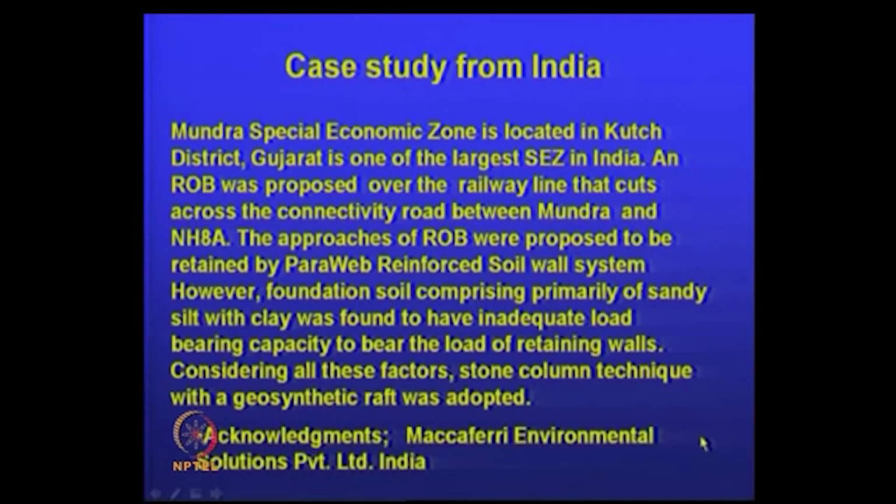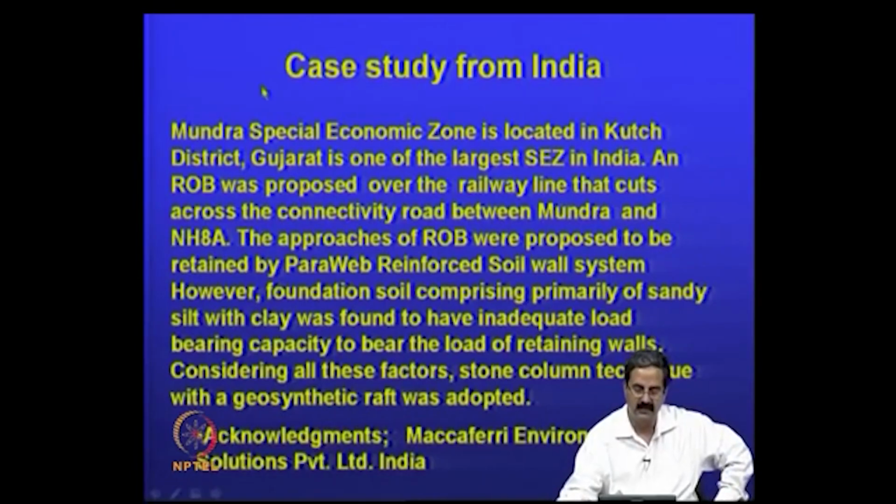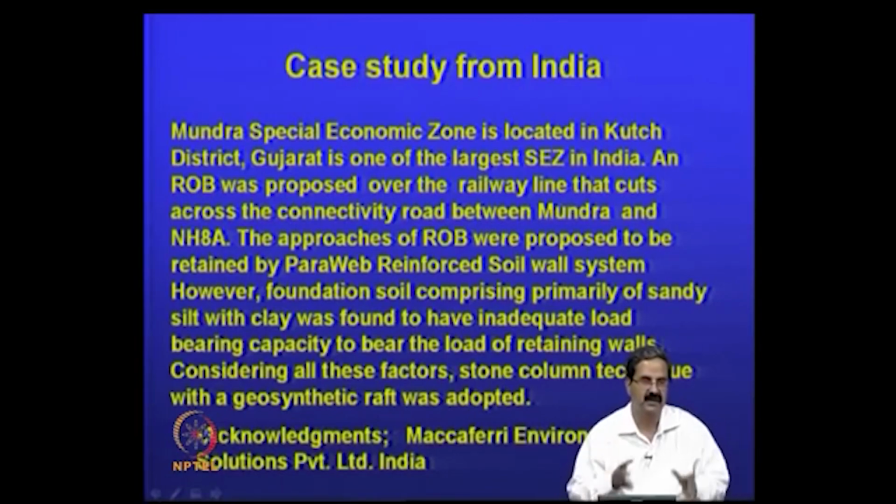Okay. There is another case study that I would like to highlight from India. Of course, we have many case studies in India also, and for example, this is in Gujarat, where they are trying to have a special economic zone, and the soil was very soft there in Kandla Port Trust. A ROB, a road over bridge, was supposed to be constructed, and the soil had poor bearing capacity. So, what they did was use a stone column technique along with a geosynthetic raft. You have stone columns, and then a geosynthetic raft at the top.